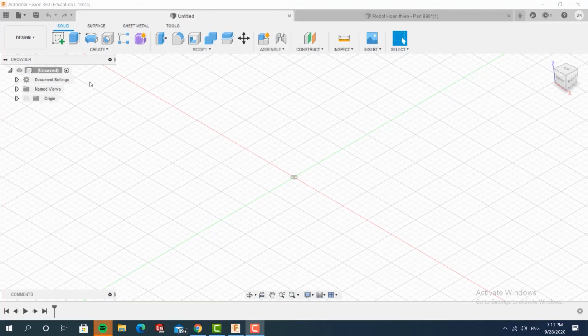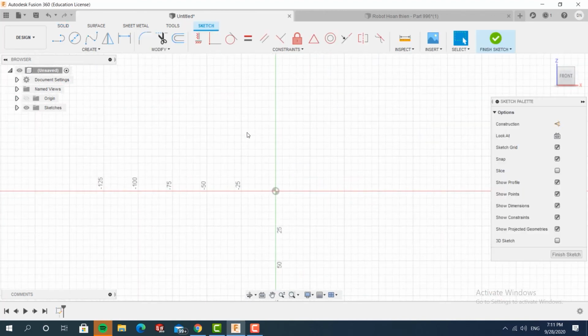Lastly, you have support beams or flange or whatever you want to call it. This is basically the simplest thing that you can use for support. Just pump out, well, a whole beam to support that part. Basically, like I said before, you don't want parts to overhang too much. So why not just use a huge support beam to just connect that part to the base?